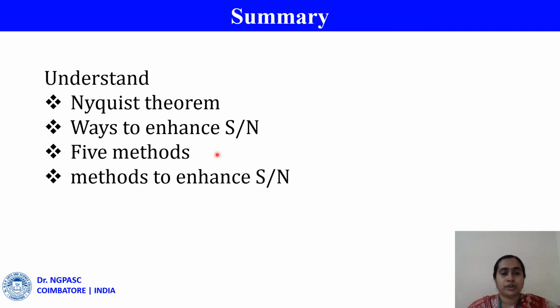We discussed five different methods, starting from filtering, integration, modulation and demodulation, active filtering, and finally the boxcar integration or the boxcar method. These methods are commonly used to enhance the S by N ratio in instrumentation to get noise-free results from the various instrumentations used.